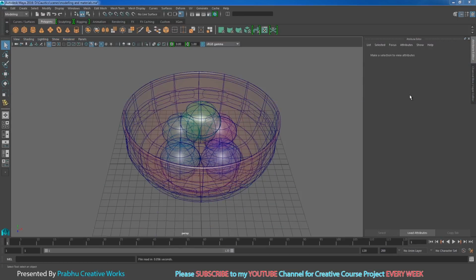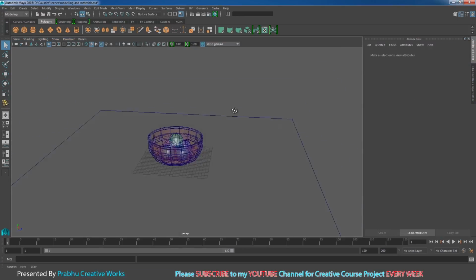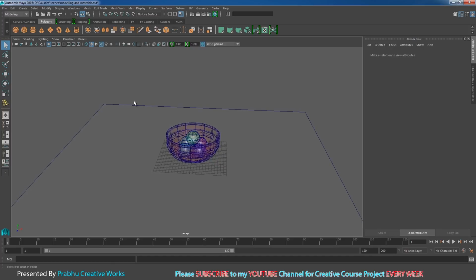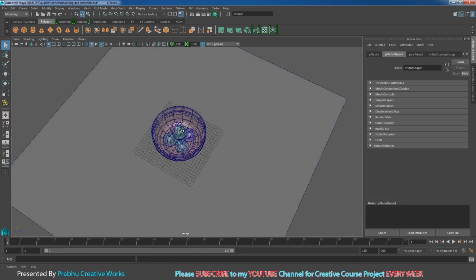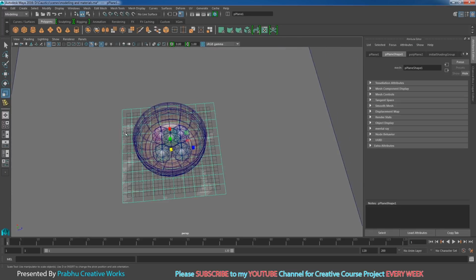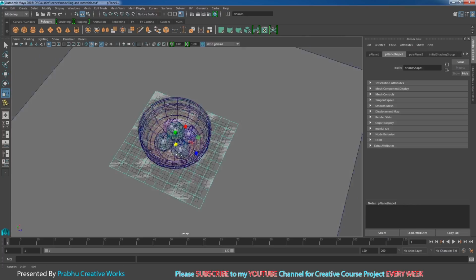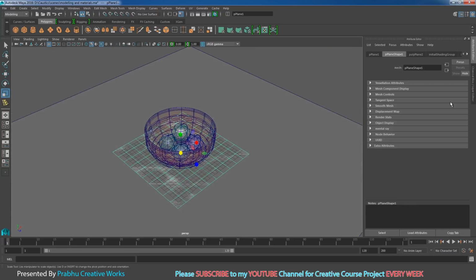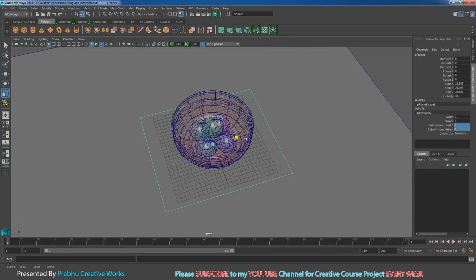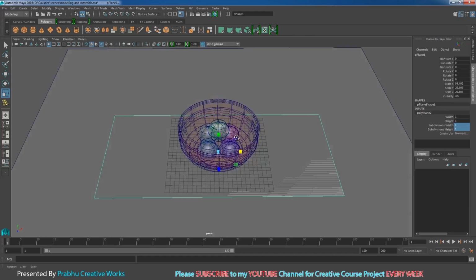Okay, before we start lighting, you want to set something for our reflective materials. So click on polyplane, so it will automatically create it on center of grid. So press R and scale a little bit big, so you want to cover the whole of our crystal cup. Now give subdivision width and height to 1. Now I want to scale a little bit bigger in X.